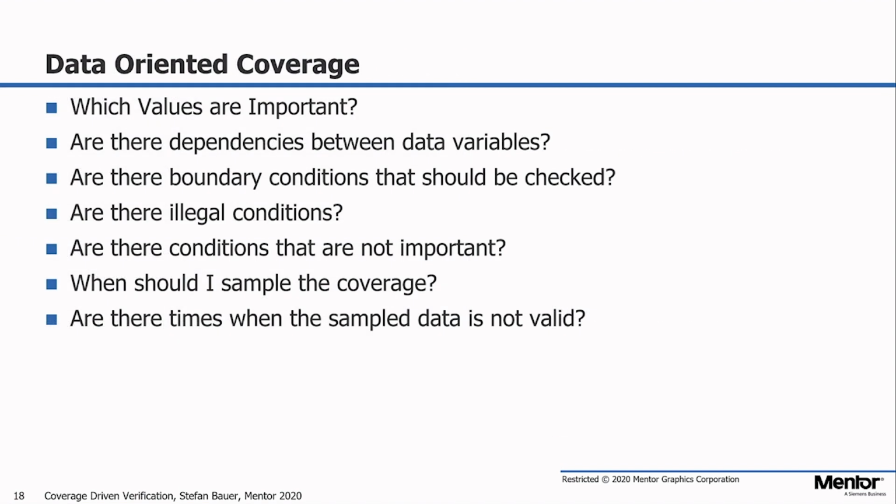Next, let's have a deeper look into data-oriented coverage. With data-oriented coverage, you need to answer the following questions. Which values are important? Are there dependencies between data variables? Are there boundary conditions that should be checked? Are there illegal conditions? Are there conditions that are not important? When should I sample the coverage? Are there times when the sampled data is not valid?